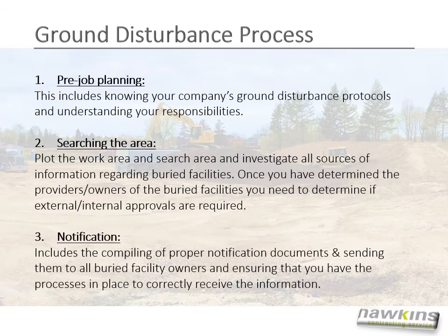To perform ground disturbance safely, you must follow this process. In step 1, you have your pre-job planning. This includes knowing your company's ground disturbance protocols and understanding your responsibilities. Step 2 is searching the area. Plot the work area and search area and investigate all sources of information regarding buried facilities.